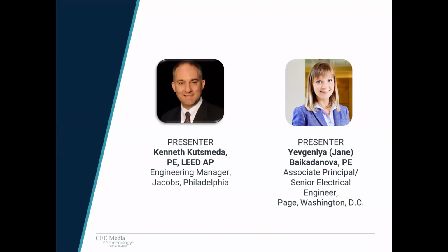Yeah, so the second part of the question is, can you talk about owner acceptance or rejection of this medium voltage distribution system? Yeah, when you try to present medium voltage to a client, I think the pushback is generally finding people. Do they have people to work on that gear? Can they get people readily available? I don't usually find it being the equipment or the size. It's mostly the people working on it. If they don't have people employed that have that experience, they now need to hire them. So that can be a new issue for them. I think that's a big issue.